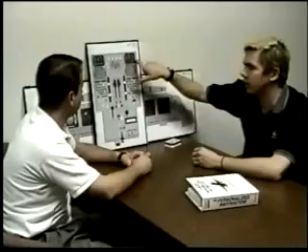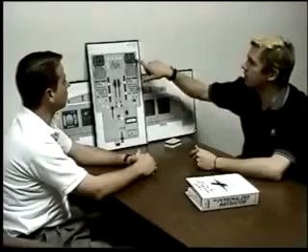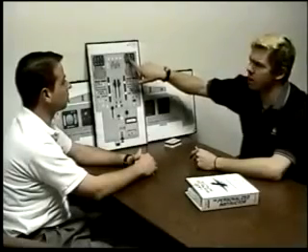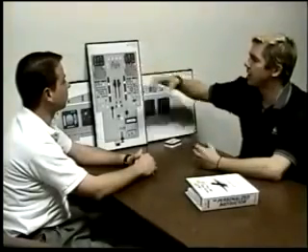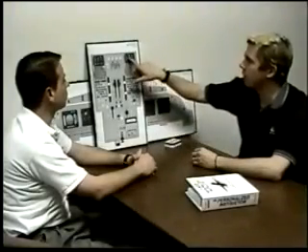I do not select config 3, however, if I'm going to land flaps 3 for an ECAM driven situation. The most frequently occurring time this would happen would be during an alternate law approach and then direct law landing. We know that every time I do an alternate law approach and a direct law landing, I'm going to be doing this in flaps 3. If I were to select config 3 here, it would change VLS by approximately 5 knots. And when we go out and figure out our configuration and our approach speeds, that'd be incorrect. We need to base this off of VLS for flaps full because that's VREF.